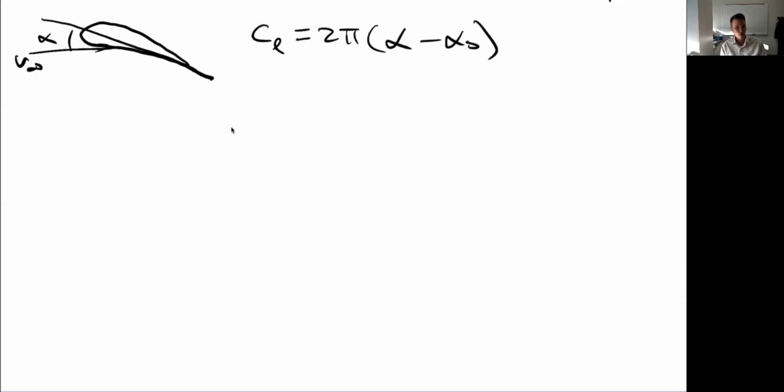We got this very useful result, but we found that for a 3-dimensional case now, each airfoil section, we could still use that theory. However, we have to reduce my angle of attack by this induced angle of attack because of the presence of the downwash, right? Because there's now downward velocity, I've reduced my angle by exactly the amount that we just calculated.